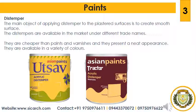So the first one is, on drying, the film of distemper shrinks. Hence it leads to cracking and flaking if the surface to receive distemper is weak. The next is, the coatings of distemper are usually thick and they are more brittle than the other types of water paints. The film developed by distemper is porous in character and it allows water vapor to pass through it. Hence it permits new walls to dry out without damaging the distemper film.